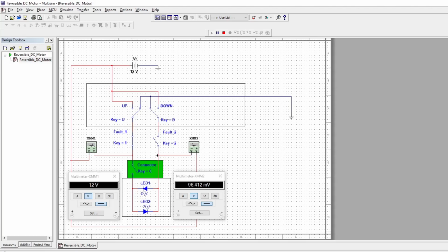And then from there, you would check it at the connector. If it had no voltage or no path to ground, this would read 0. And if you moved up to this pin on the switch, for example, and then all of a sudden you had that 12 volts, well, you know that this path to ground is good. So the fault would be between this pin and this pin, as an example.